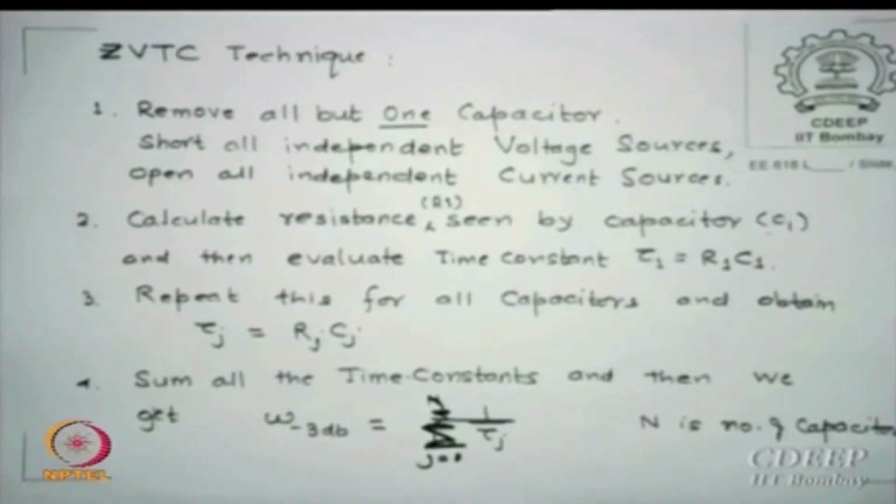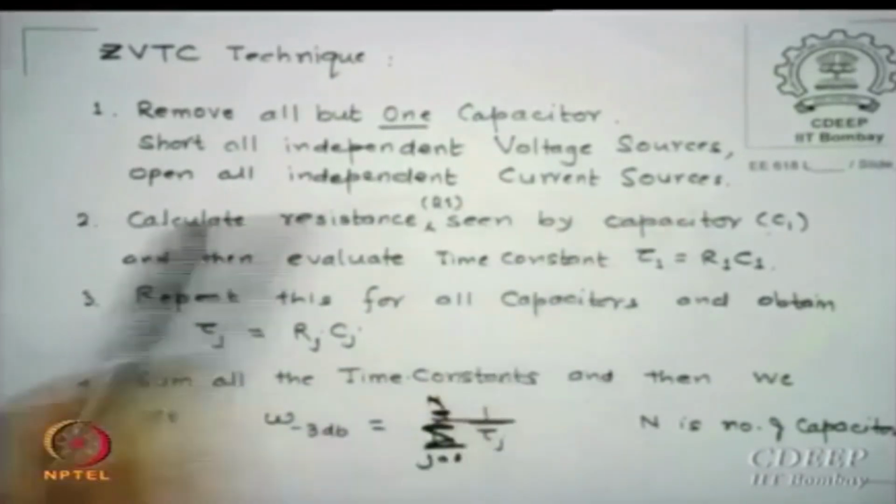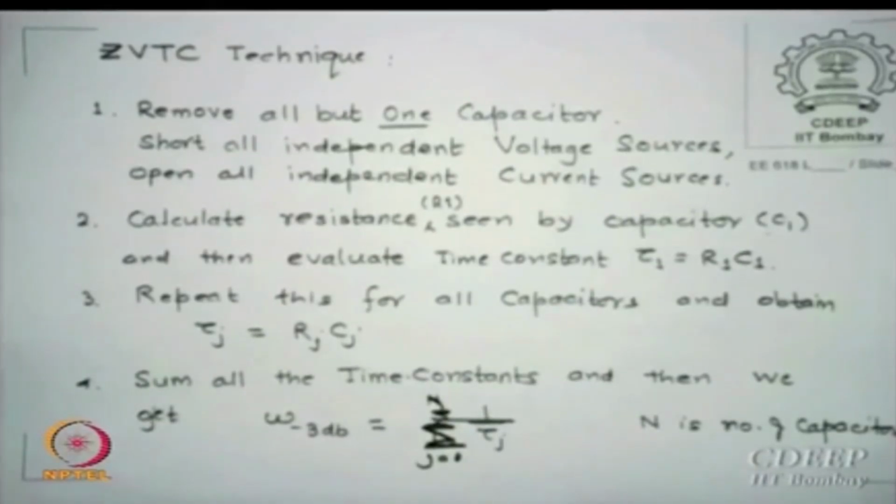Open circuited means actually the impedance is infinite, so just open. There is another technique which I will show you in which capacitors are shorted, as if C is made infinity, so all capacitors are now as if not existing. Okay, and short all independent voltage sources.